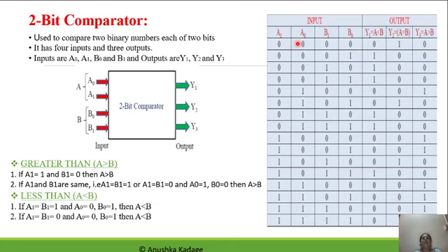To write that, first we will consider that when B1 and B0 are taking 4 different combinations, at that time A1, A0 remain constant. According to that, for the first 4 rows, we have kept A1, A0 constant at 0, 0, but B1, B0 we have changed from 0, 0, 0, 1, 1, 0 up to 1, 1.